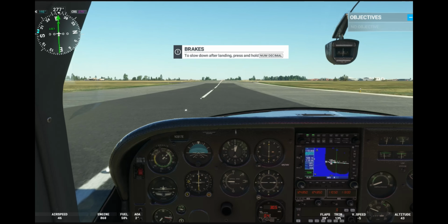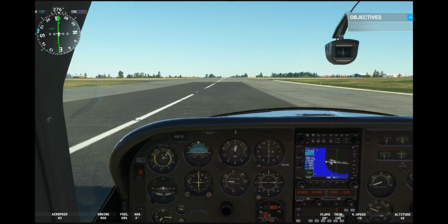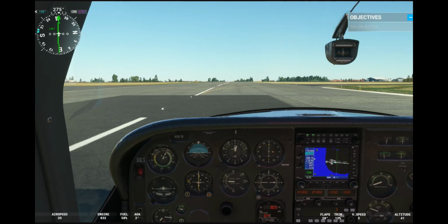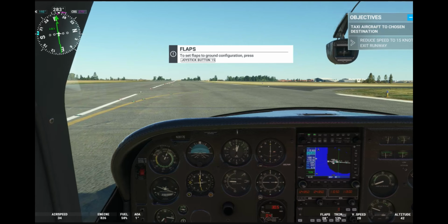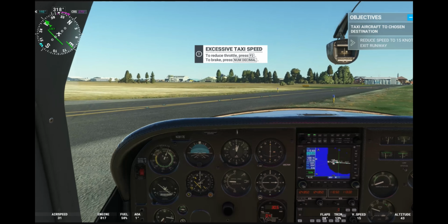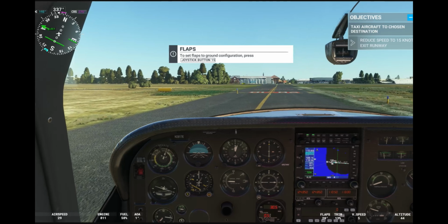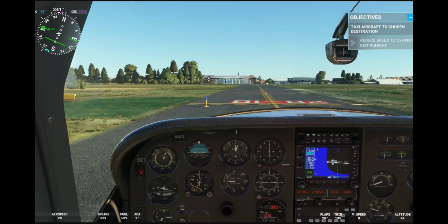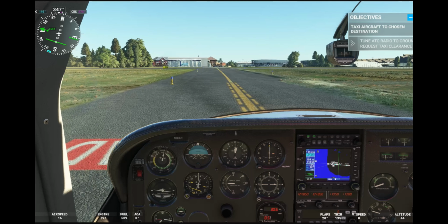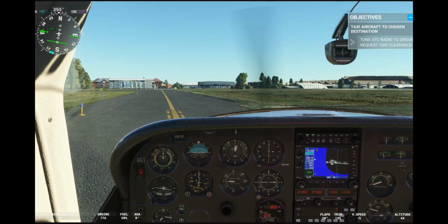And the next thing we'll do is exit the runway to the right. And when we do come to a stop, we can put the flaps back up, because flaps can be damaged during taxi with bits of debris flying up into the flap holes.